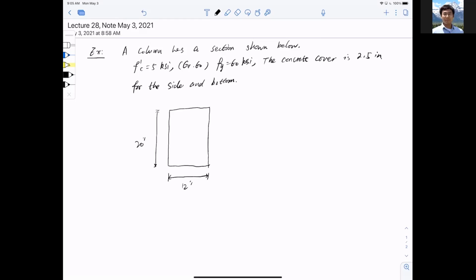Okay. Now we have stirrups, and the stirrups go through it. I should be careful because this is a column, so I call them ties, because they're closed loop stirrups. I have 4 bars at the corners. And it is clear that the tie is number 3, so you don't have to guess or worry about the diameter. It's number 3, so it's told you already.